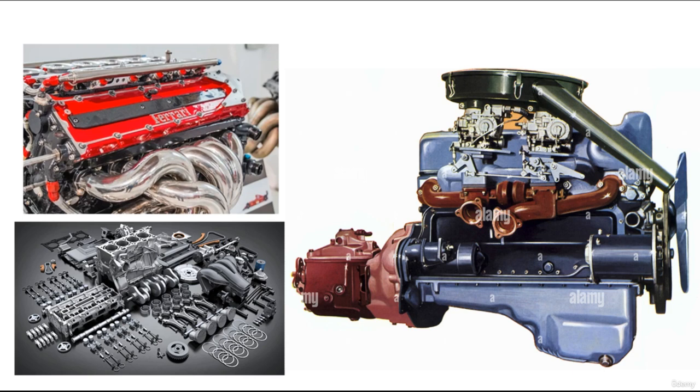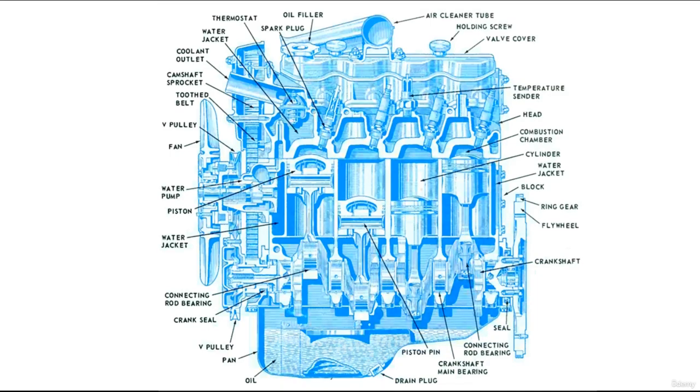The biggest part of the engine is the cylinder block. The cylinder block is a large casting of metal that is drilled with holes to allow for the passage of lubricants and coolant through the block and provide spaces for movement of mechanical parts. The block contains the cylinders, which are round passageways fitted with pistons. The block houses or holds the major mechanical parts of the engine.